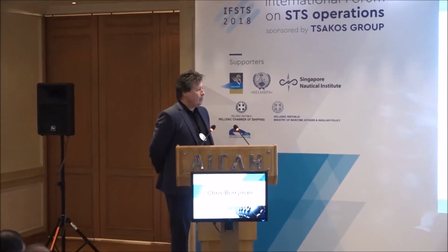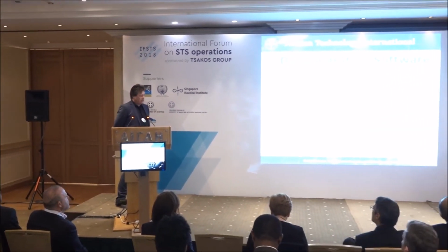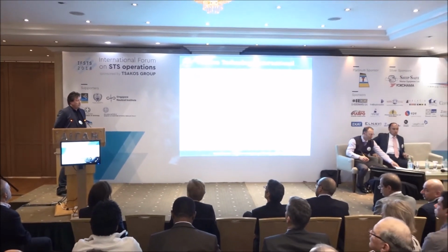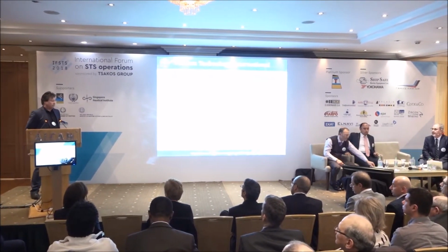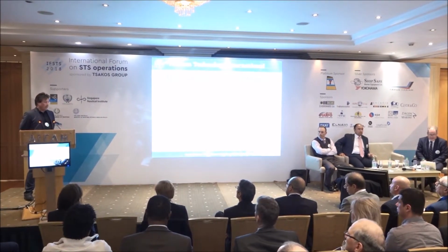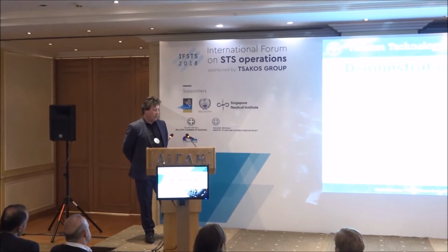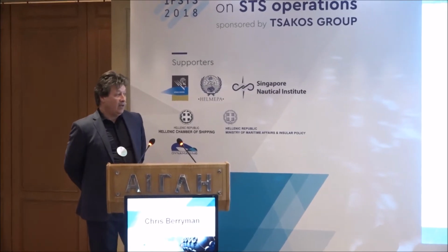Conscious of the time, but one quick question. Do you do post-incident analysis? Yes. From your experience, what has been the cause? Is it the poor quality of the mooring lines, the fenders? In my experience, the mooring lines are always in a less than good condition. For all the investigations I've done, people don't inspect their mooring lines. They generally don't know how to do it. I did one last year. The total claim was $80 million. The lines were down to about 28% of their new breaking strength, and the vessel crashed into the jetty and just totally wrecked it. Yeah, so that is the most common reason.